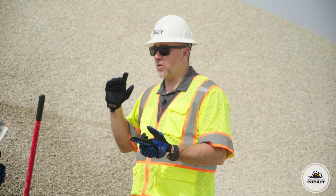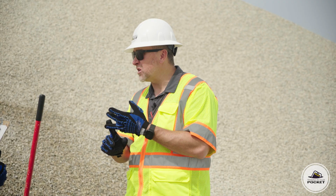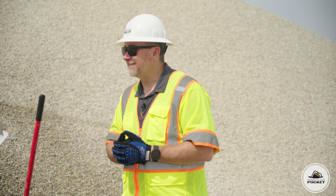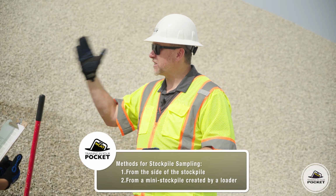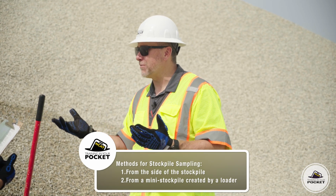So we could sample from conveyor belts, from discharge points, from transportation units, from the roadway maybe, or from stockpiles like we have here today. So what method are we using today? We're going to use two different methods today. We're going to use the method where we sample from the face of the stockpile, and we're also going to use a mini stockpile created by a front-end loader.